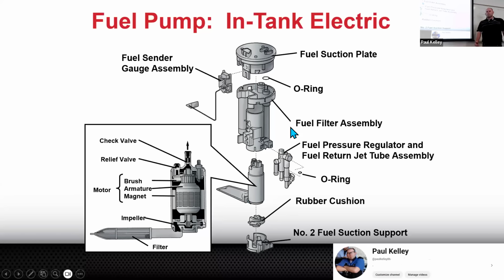I've even seen where a customer will bring in the car for a crank no start, and if the fuel level shows low, I don't know if it's a bad pump or if it's low on fuel, I'll literally grab the vehicle and rock it like this, and then boom, if all of a sudden it fires up for a couple seconds and then dies, it's like, hey, you're just low on fuel. Me sloshing it around may get a little bit of fuel sucked up by the sock. It can too, yeah.